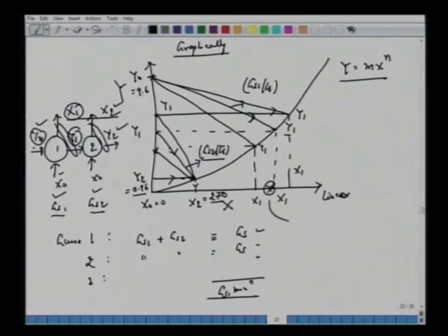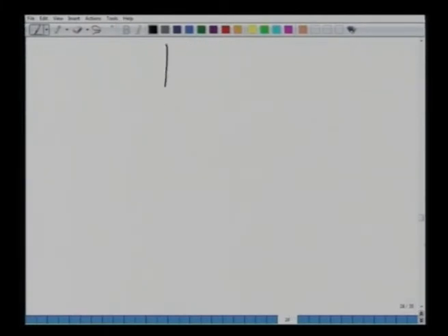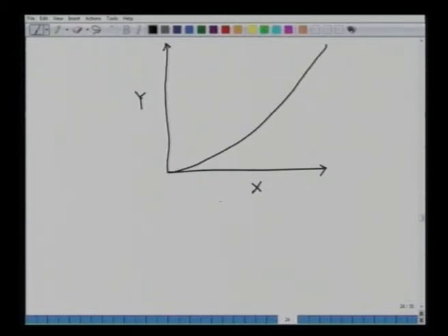Maybe this is x1, which should be equal to 565. And alright, so this is your x1, and what y1 you will get here, this was 0.96, corresponding to this 565, this number will be 3.3, same as before. So let's redraw this curve again, assuming that we have reached the right guess, right values, which give you the minimum amount of solvent or charcoal, solid. So we have this equilibrium curve. We start with y0, x0.